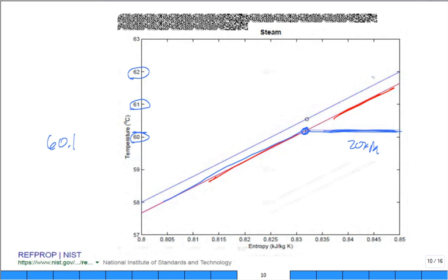All right, what's this blue line right here? A different pressure. It's not 10 or 20 kilopascal. What's the pressure of that line? 8,000 kilopascal, or 8 megapascal. So you are absolutely right. It was constant entropy. And the outlet of the pump is right there.